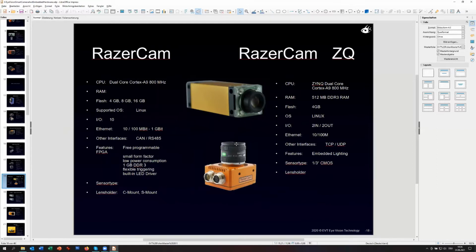Which manufacturer is the best is another question. Maybe the housing size is a good option to select the right smart camera. Here, for example, this yellow one on the top is 20 by 20 by 40 millimeters. So it's a very small smart camera if you need a very small one. And of course, you don't get every smart camera with every resolution. Either you select it based on the resolution you need or based on the size you need. The combination. So there is the basic choice. At the end, the programming is always the same.